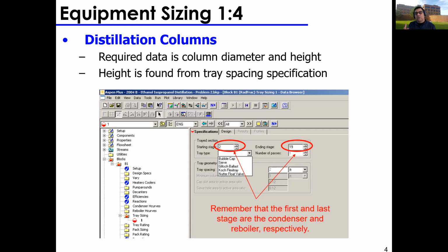And then in order to determine the height, you're gonna say that every stage is 3 foot high, right? And this depends on the tray technology you're using. And now, as we're getting into height, we're starting to look at more details of the type of technology we're using. And if you look at Perry's manual or other books, you're going to find all these details concerning the height of each tray, depending on the flow rate, and you can get estimates for the height you want to use. But usually a tray height is 3 foot, 6 foot, maybe sometimes 9 foot in very unique cases.